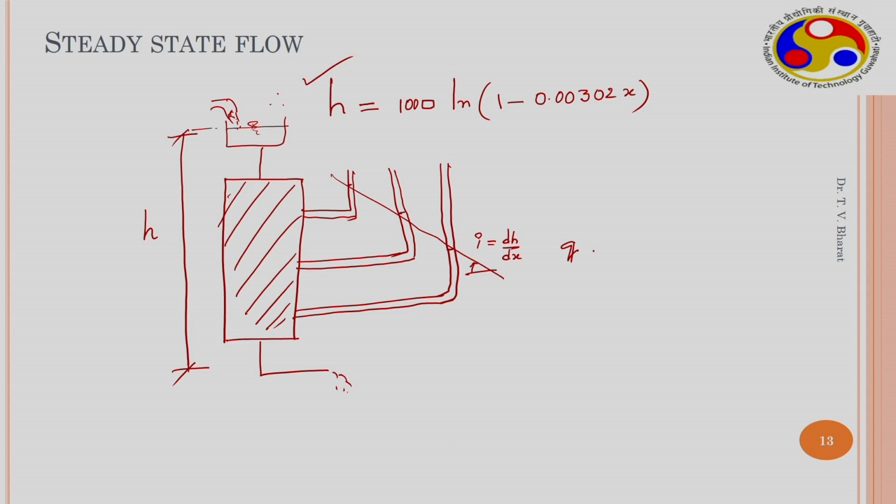So the variation of Q with respect to hydraulic gradient should be directly proportional, because Ks is independent of hydraulic gradient. So when the estimated hydraulic conductivity remains the same with change in the gradient, then the soil is saturated. If that is not satisfied, but you are getting a constant flux, that means your soil is partly saturated, but there is a steady state flow taking place through your soil sample.